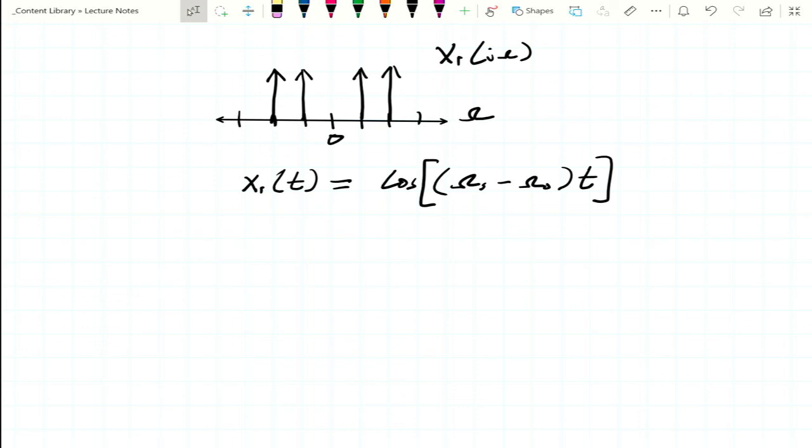Edward asks, if we're limited with our sampling rate, is there a way of doing additional processing with the aliased wave to arrive at the original signal, or would that require knowing the frequency of the original signal, which is what we're looking for in the first place? Yeah, so there are anti-aliasing techniques that let you kind of get away with this, but it does require knowing some things about your original signal.